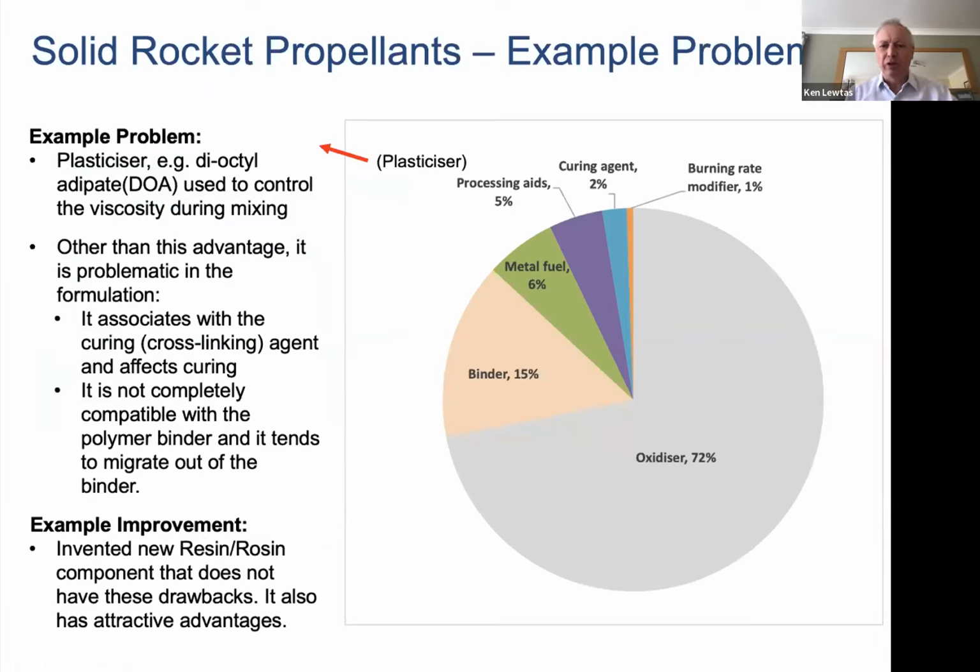If ever you've looked at a label stuck on with the pressure-sensitive adhesive, after a few years, you can see the oil that's put in a pressure-sensitive adhesive migrating out and even through the paper. Or even if you have something like a kitchen implement that's been over-molded with the rubber, and a few years later, it becomes sticky. This is because they formulate the rubber with a processing oil, and this slowly comes out over time. And I'm pleased to say, by looking at this scientifically, we've actually invented a new resin here that we can put into these things, which doesn't have these drawbacks.